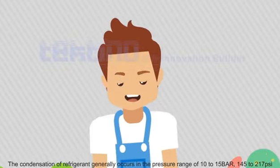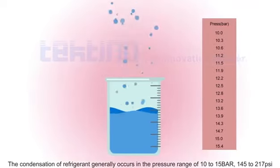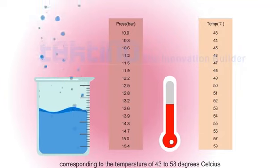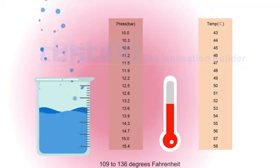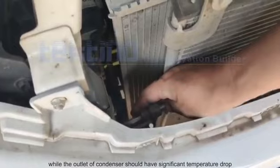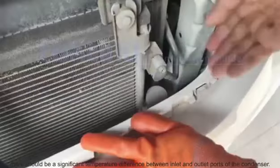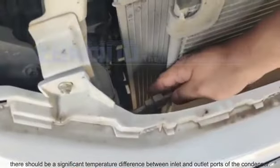The condensation of refrigerant generally occurs in the pressure range of 10 to 15 bar, 145 to 217 psi, corresponding to the temperature of 43 to 58 degrees Celsius, 109 to 136 degrees Fahrenheit. The inlet of the condenser is very hot, while the outlet of the condenser should have a significant temperature drop. That is, there should be a significant temperature difference between the inlet and outlet ports of the condenser.